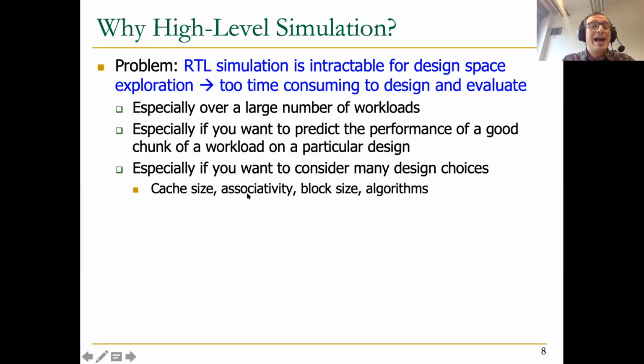And if you want to have an RTL implementation of the cache, plus an RTL implementation of your processor, and look at all of these design choices, try to explore all of them in a real workload that you want to execute for a long enough time, let's say 10 seconds of real execution time. Ten seconds of real execution time on a real system actually takes much longer in an RTL level simulation, because an RTL level simulation is really simulating what's happening at every single gate that you have in the system. So you won't get very far.